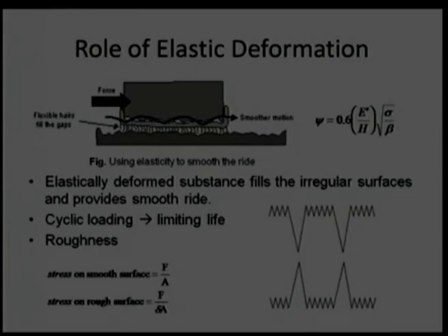Now, this whole slide was related to surface roughness, hardness and Young's modulus. It has been experienced that surface roughness plays a major role compared to the other properties, Young's modulus and hardness. The reason being, surface roughness will continuously change. Initially, maybe the surface roughness has a value of 1. After some operating hours, the surface roughness value will change. It may be on the better side, maybe on the worse side.